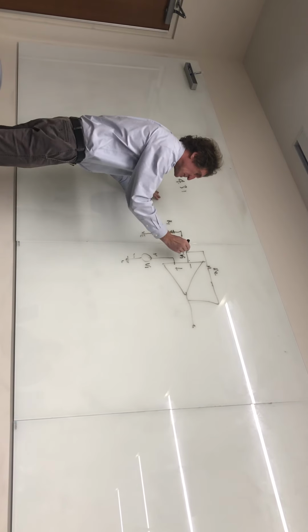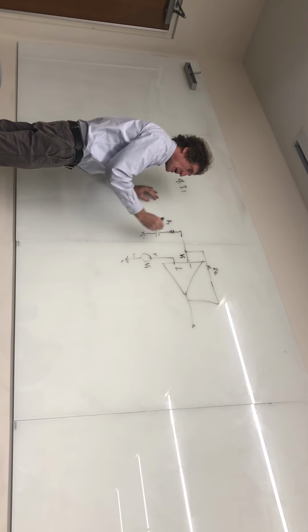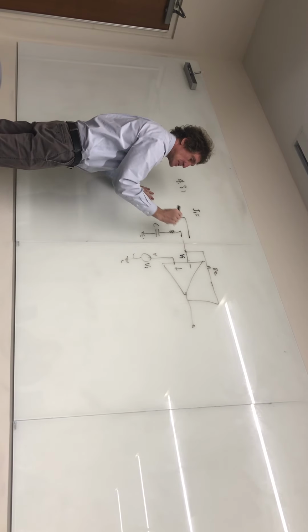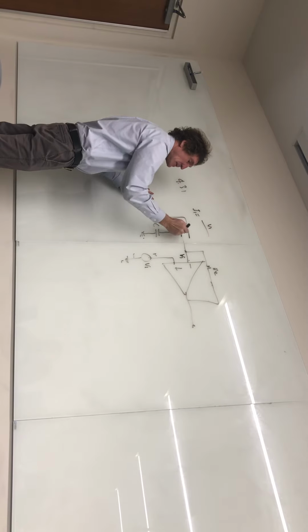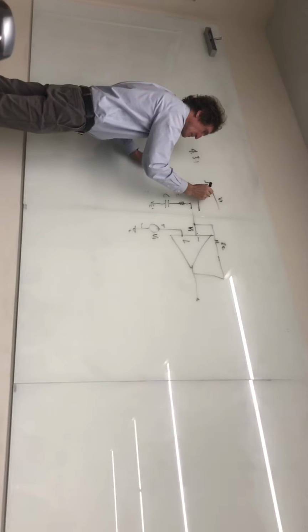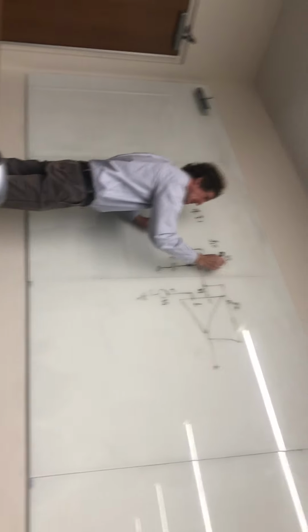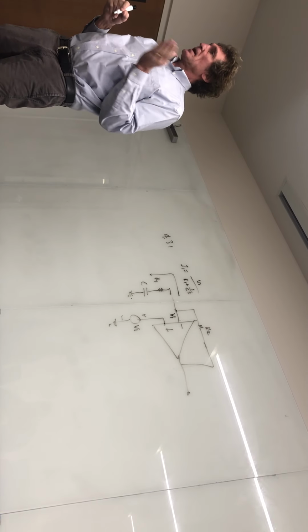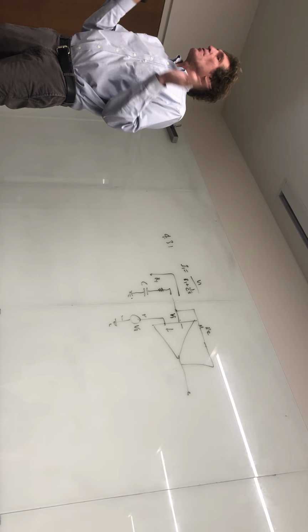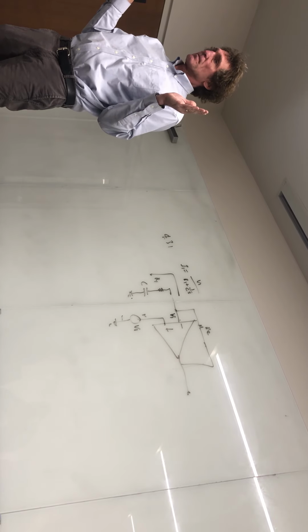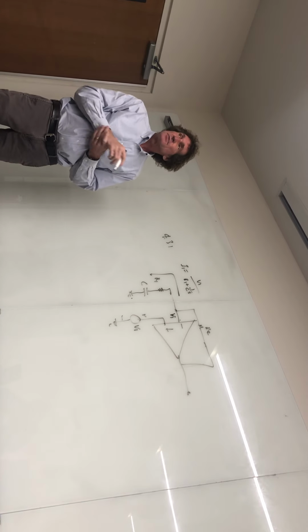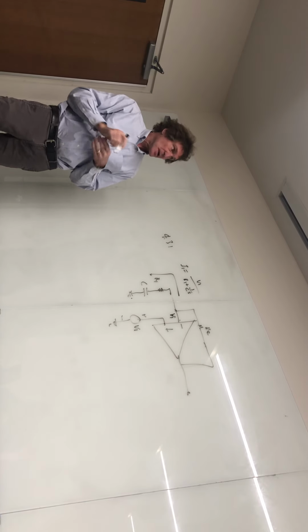Once you have that, next thing you look for is currents. If I know that voltage is between here and ground, then I know this current, and I'll label that as I1. I know that's going to be simply VI divided by this impedance. That impedance would be R1 plus 1 over CS. Remember, we work in the S domain, so the impedance of the capacitor is 1 over CS. There are no initial conditions with these, so you can throw out anything that has to do with the initial conditions when you do the Laplace transform.